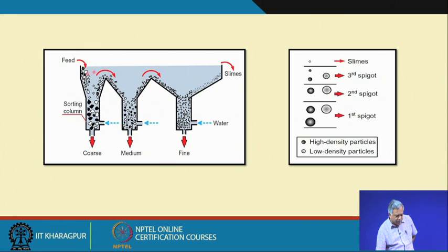You have a mixture of 100 micrometer to 10 micrometer particles, and I want discrete size products. If I know the settling velocity of the different discrete sizes, say for 100 to 80 micrometer particles the settling velocity is, just for discussion's sake, 5 millimeter per second, then I will have my rising water velocity at around 4.5 millimeter per second.